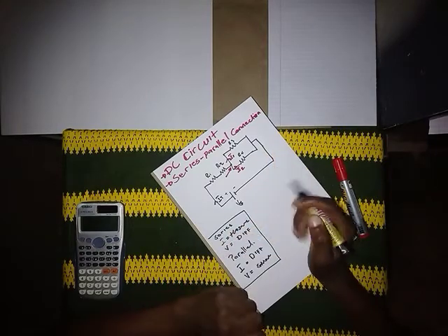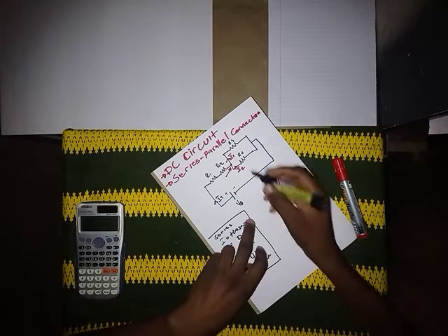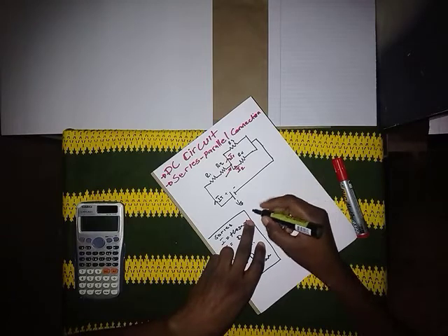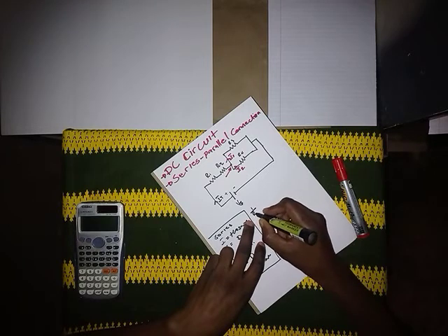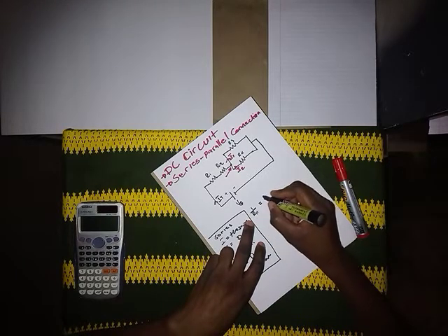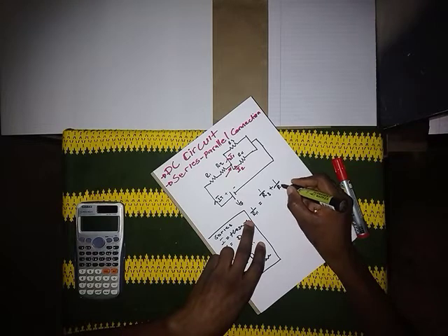We have to calculate it separately. What I prefer doing is starting with the parallel first, then doing the series, because after simplifying the parallel, you can just add it with the series, which is way easier than starting with the series. So for example, this one we have to do the parallel first. We have to say R parallel is going to be 1 over R3 plus 1 over R4.